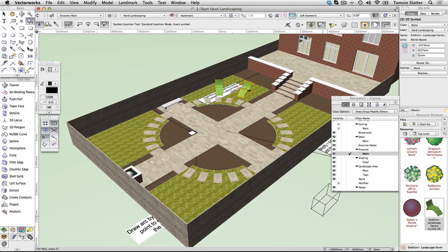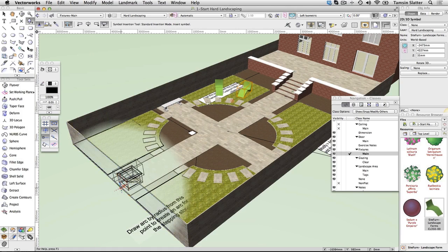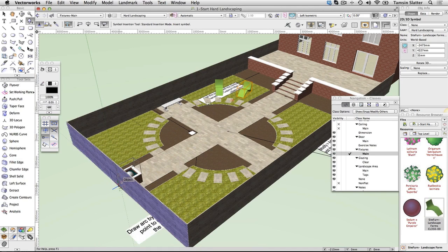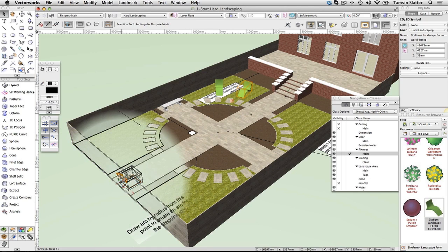Examine the water feature. Press B again to invoke X-ray mode on the lower left of the garden to see through the fence. On the left end of the horizontal path is a water feature that's been created for you. Select each of the elements in turn with the selection tool and examine its properties on the Object Info palette.